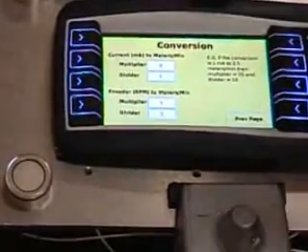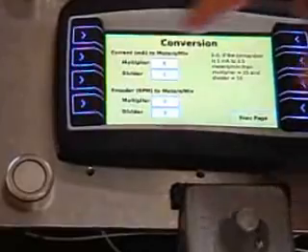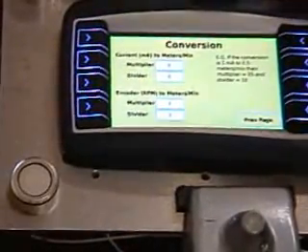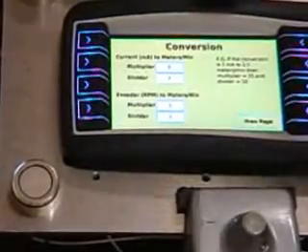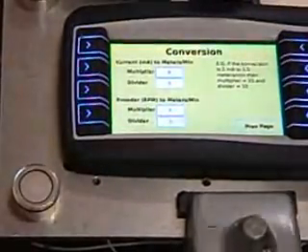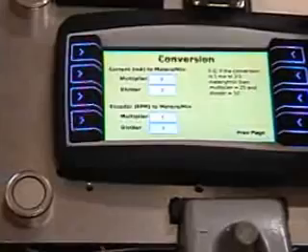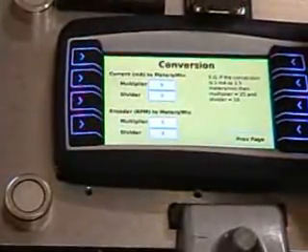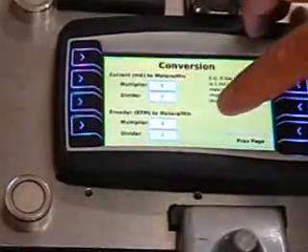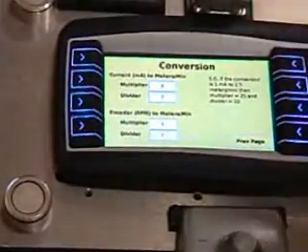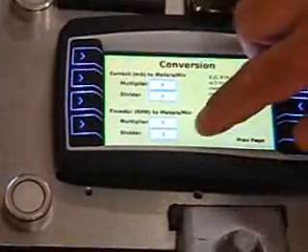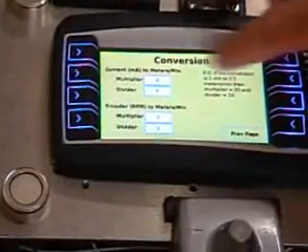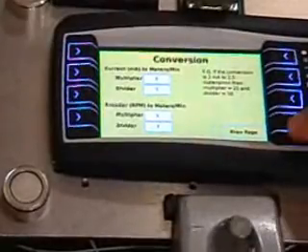If 1 milliamp is 1.5 meters per minute, we'd keep that one at 3 and we'll put this one at 2. And now that basically means 1.5 meters, every milliamp is 1.5 meters per minute. Similarly with the encoder, RPM to meters, it works the same way, so you set up the RPM multiplier and divider accordingly. We'll leave them at 1 and 1. We'll leave these ones at 3 and 2 if you like for now.